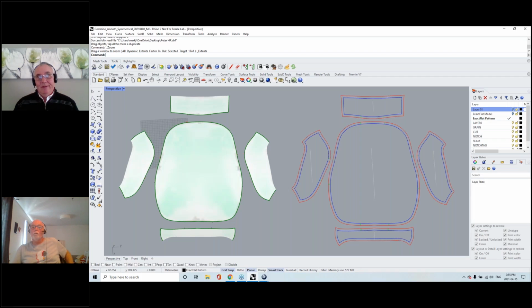So if you have a 3D model and you apply a texture to it, we can create the flat patterns of the texture, so the graphic along with the cut file. We can save that out as a PDF or as a TIFF or a JPEG, and the uniqueness with the PDF is that you get the graphic information and the cut information all in one file. So you can go to a dye sublimation printer and print the graphic and then cut that. So yes, paint protection film is one of our fortes.